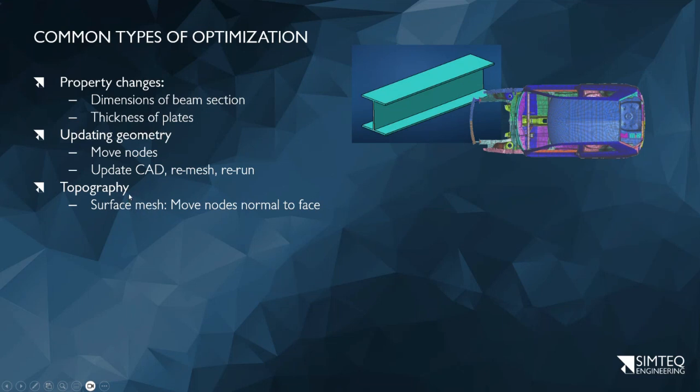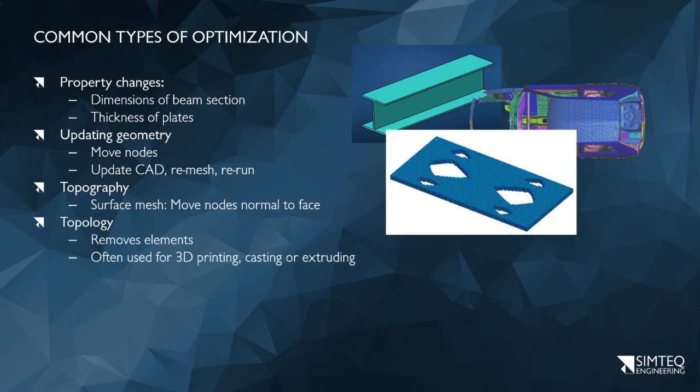Again, topography is not just a random movement, because if I move one node up, one node down, one up, one down, that's not really physical. I won't be able to manufacture something like this. So we have to in some way specify the size of features, or minimum sizes of features, to be able to do that.